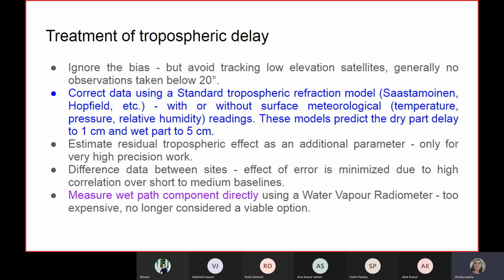So what is the elevation angle of zenith? When the satellite is at the zenith, what is the elevation angle? Can anybody answer? Ma'am, 90 degrees. Yeah. So you understand, from 20 degrees to 90 degrees, we may use this information in computing the position accuracy. So this will not affect much. This can be ignored for most practical applications.